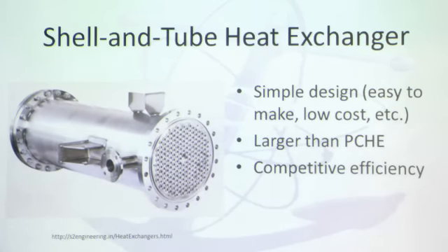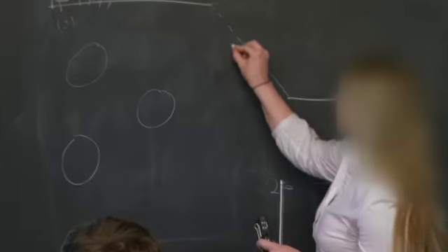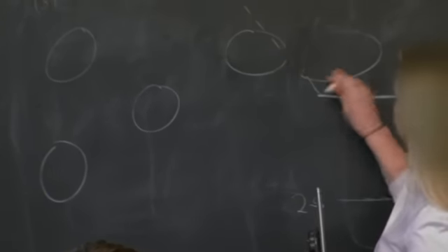Additionally, the picture did not come out here, but instead of a square aligned geometry, we're going to go with a triangular geometry, so that the lead bismuth flow through the tubes will be better. I'm sorry the picture didn't show up, but maybe if I draw it here. It's more like this rather than like this. So that when the lead flows through the subchannels, it has a better flow.